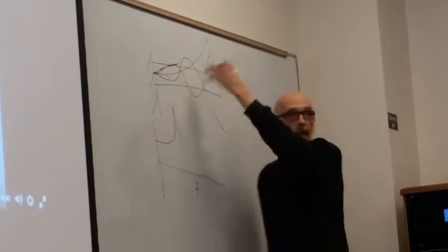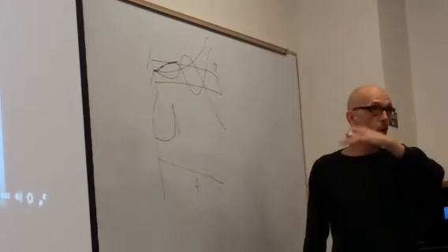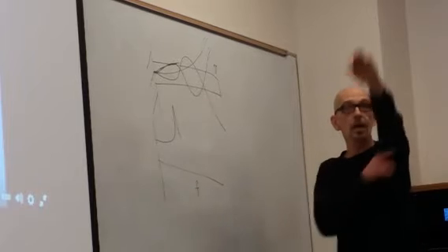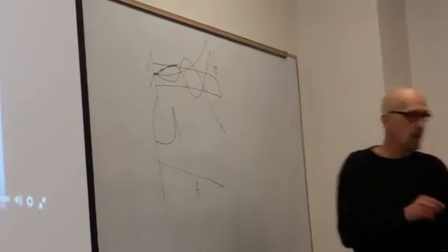You're seeing the middle of the wave also go up and down. It's not just going like this, it's going like this. Watch again. The middle's going up when the tip is going down. All right, that's actually the second mode of this thing. So a model for this thing might be a two-mode model.